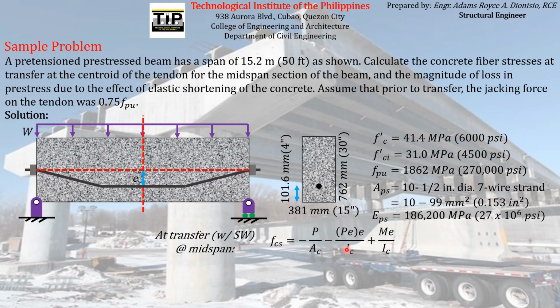while ago. So again, this is just similar to the formula for finding the stresses on the pretension zone, which is the zone which initially experiences tension as the concrete beam supports its own weight. So this is the pretension zone, the lower portion of the concrete beam with respect to the neutral axis or centroid. And since the stress we are concerned with is located here, same location as the pre-stressing reinforcement at midspan, we just have to replace c here, the distance from the centroid or neutral axis to the